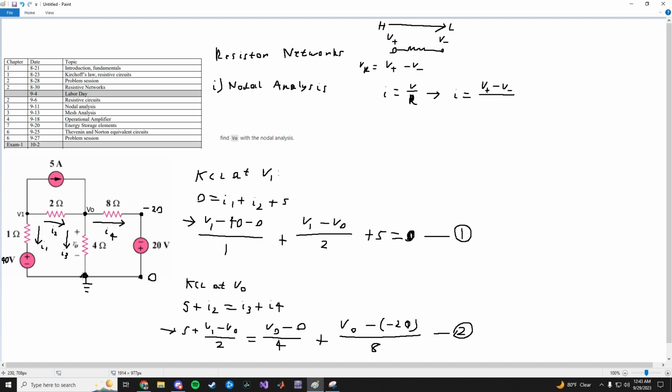It's just easier away from all these unknown nodes. So you will usually pick it here at the bottom. Second, you draw your currents as such. By convention, that determines how you subtract your potentials. So you just follow the arrow. It goes from high to low. And then that's this step.